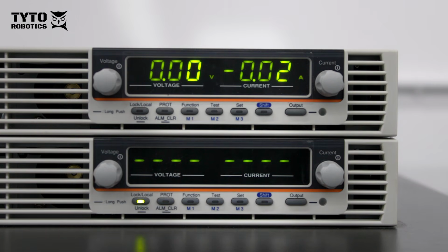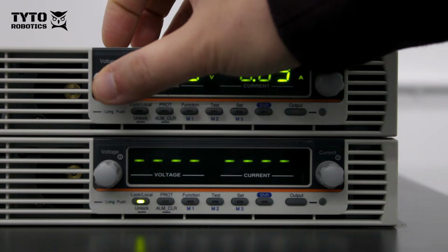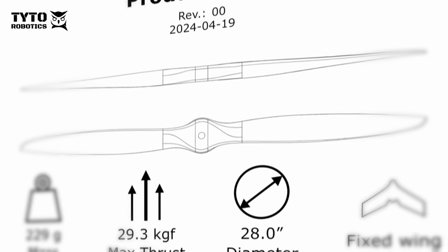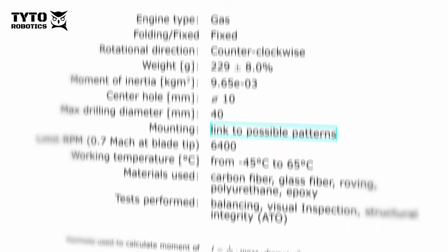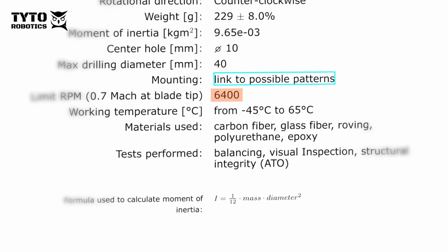We were also limited by the power supply we had available. The day before our experiment, bam! The power supply crashed out, so we had to go with a smaller one, which was limited to 45 volts. We achieved the maximum rotation speed of around 3,900 RPM, though our propellers are rated for up to around 6,000 RPM. Our motors can normally handle up to 66 volts, so the test was voltage limited.